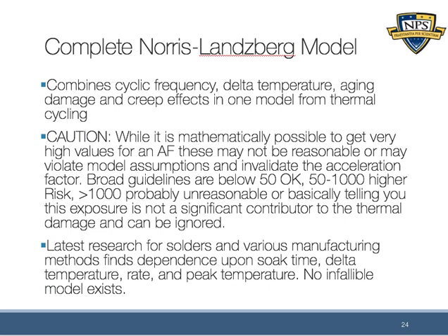But the point is that it's important to understand that you can only go so fast. Your temperature values can only really be so big. You can't subject a part to 500 degrees Celsius and negative 200 degrees Celsius. I mean, there are some natural limitations to test chambers, to the components. You don't want to destroy the component. You're trying to precipitate a failure mechanism.